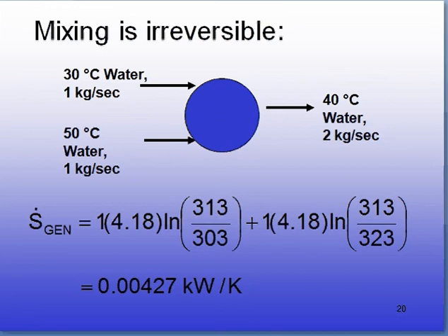There's the entropy change of that. By the way, you could take the entropy for these streams from your steam tables, approximating the entropy as that of a saturated liquid. You'll come up with the same result. In fact, I recommend you do that.